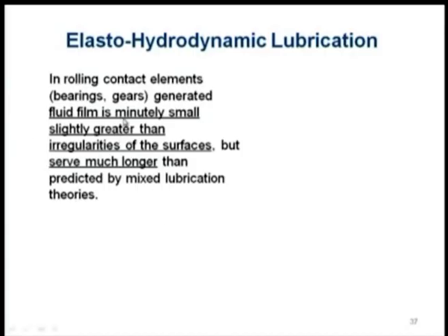The fluid film will not be very high, the liquid lubricant film will not be dominating, and whatever simple theoretical analysis we do, we get a film thickness of much lesser magnitude, but in the actual case when we do experiments, we find the film thickness is on the greater side.